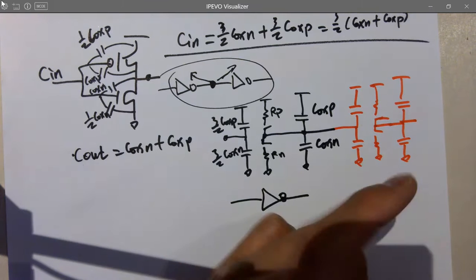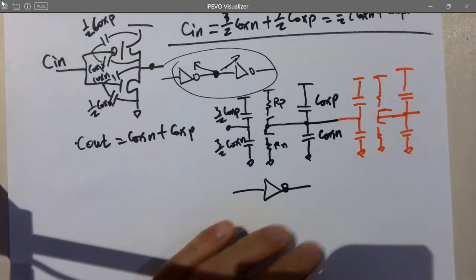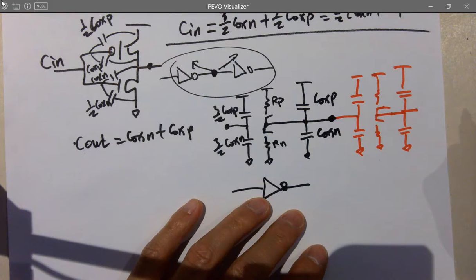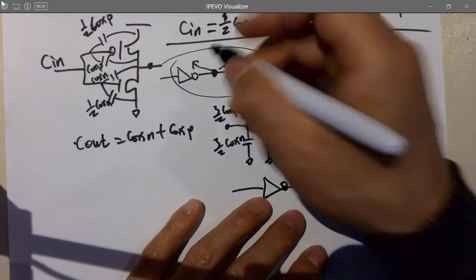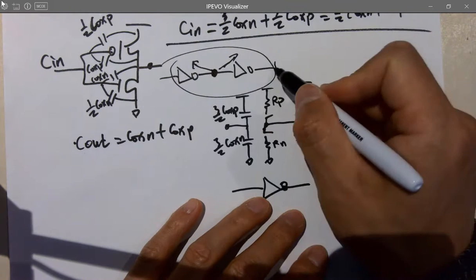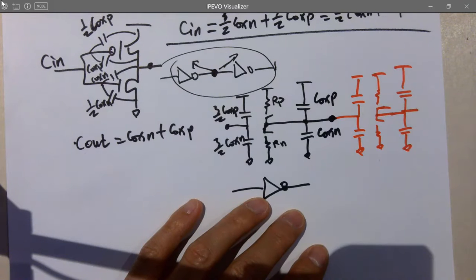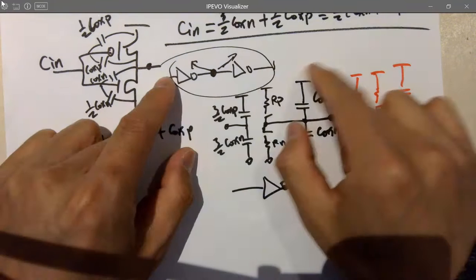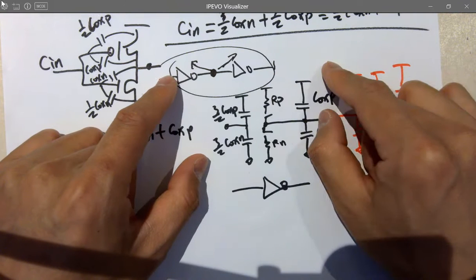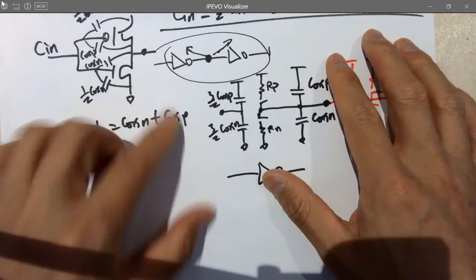That's the second inverter, okay? And when we are trying to calculate the time delay from this point, because these are the voltage nodes, that's one of the nodes. If you have a ring oscillator, you have a few others, and then close the loop. I'm going to show you why it oscillates later, but now just look at one node.